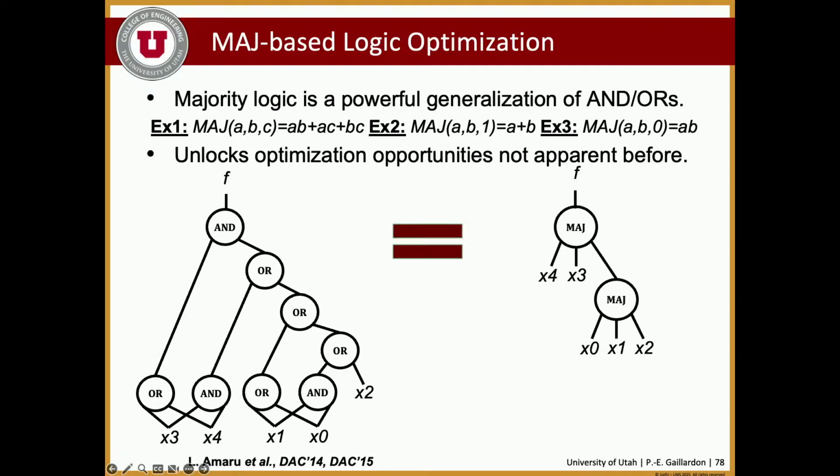And this is a full adder represented in a Boolean network of AND and OR gates, what you typically find in logic synthesis tools, right? Now, if we change that representation, you only get 2 nodes instead of a bundle of nodes. And can we manipulate that further? That's pretty interesting, and that was really created to deal with these controllable polarity devices.